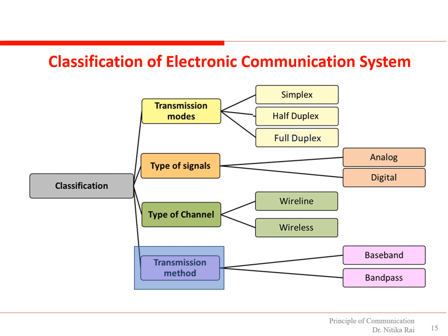And these signals are what we call baseband signals. These can be transmitted over copper wire or a twisted pair cable. And if that is the signal frequency that is being transmitted directly over a communication system, such communication systems are called baseband communication systems. However, baseband communication systems allow only short distance communication. Also, such signals cannot be transmitted wirelessly.